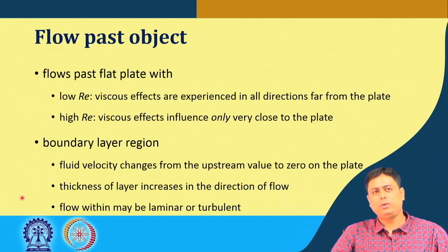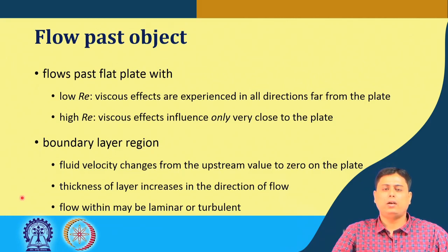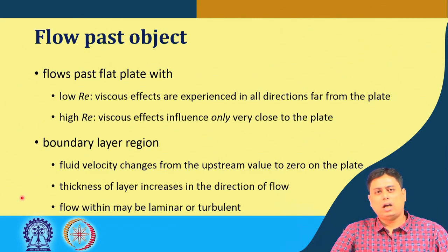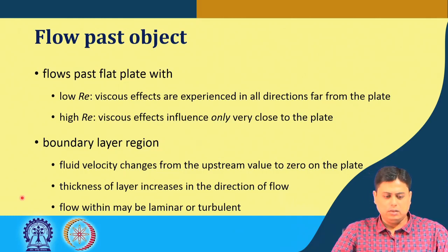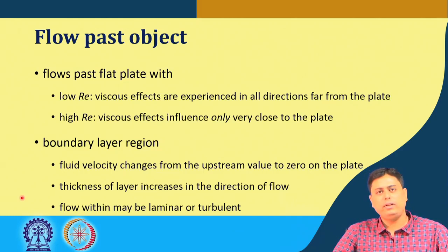And in fact, if you remember, for such a scenario the region of the boundary layer is basically much larger, and it starts far from the upstream point, from the leading edge in fact. So, the thickness of the boundary layer is also high, fine, but for the high Reynolds number cases, the viscous effects influence only very close to the plate.